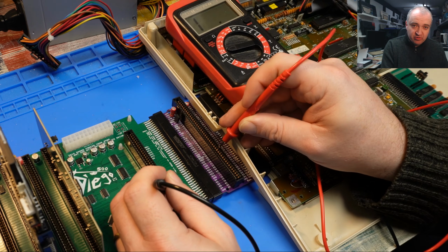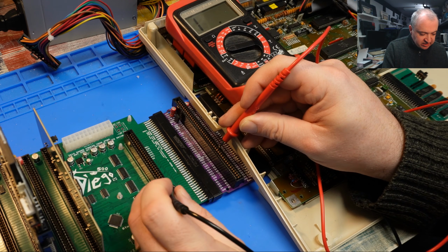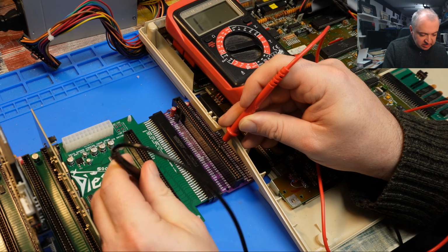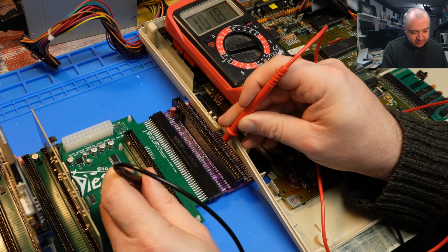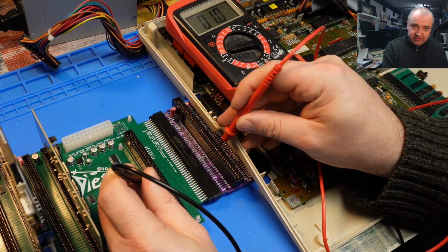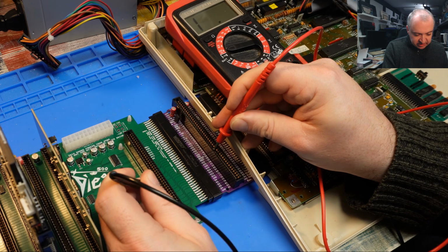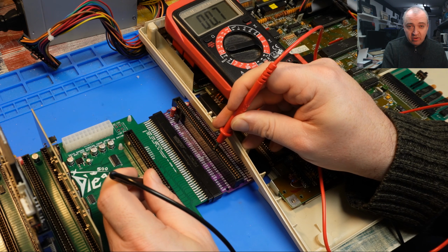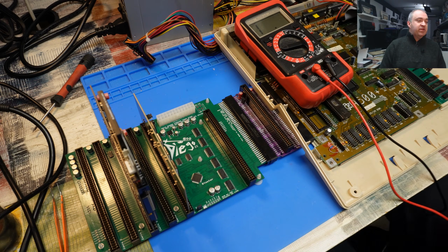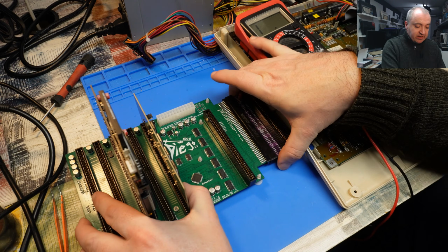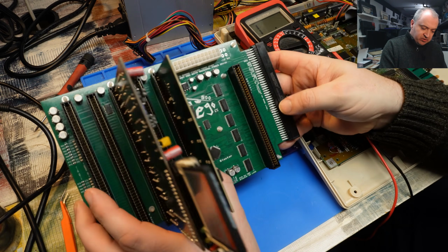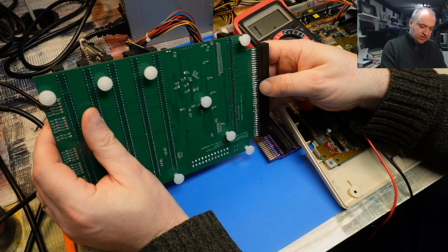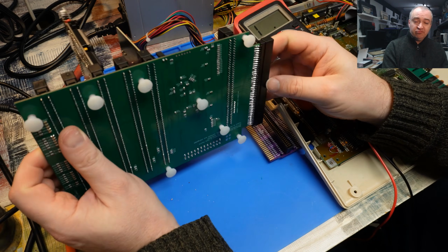But that is until we get to that point, where instead of making connectivity on the right hand side of our socket there, it's making connectivity on the left hand side. And equally, if I move this one across to the left hand side and this one across to the right, that's our problem. So yeah, bit of a problem, but hopefully easily fixed. All we need to do is lift the associated pin there and there and just run a wire between them.